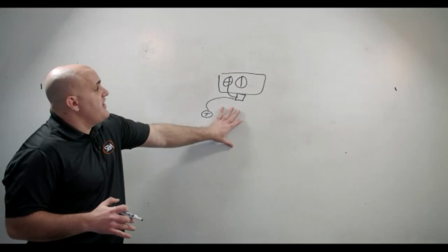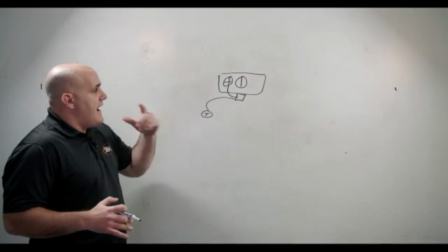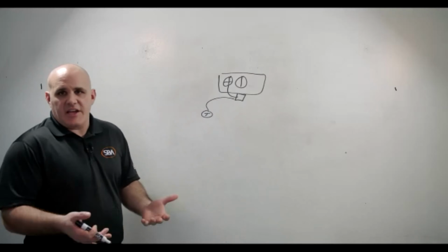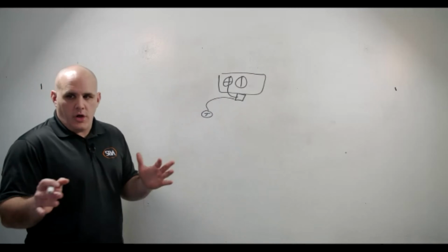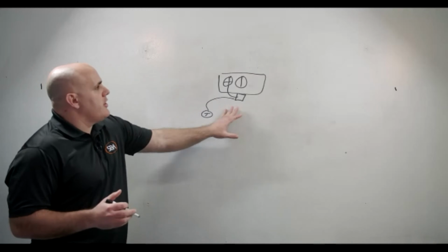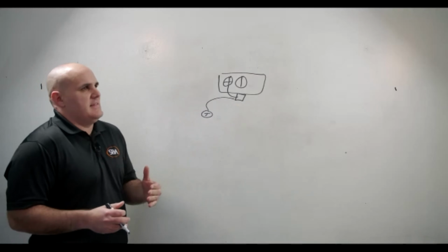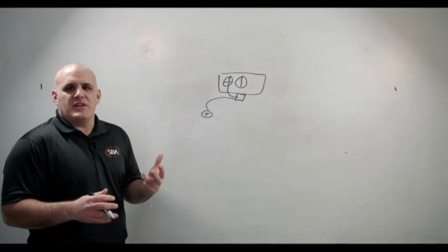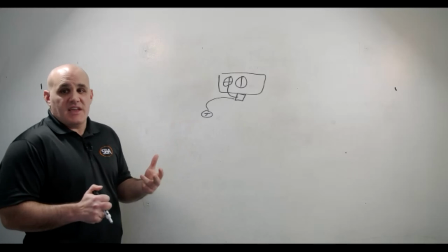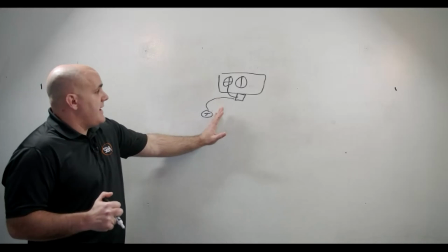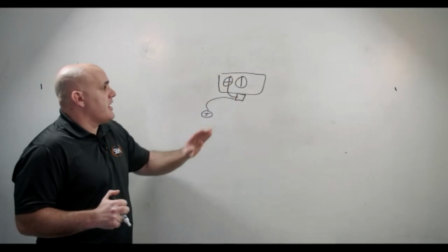All right, so with this VAV box, right, first off, VMA is an application-specific controller, right? It's got the actuator built into the controller. We're all aware of that, right? Okay, awesome. So we've got this controller, and it really has, if we're honest, two points, I would say, that we can go and really change things up, okay? So the first thing is our temp sensor, and then the second thing is going to be our airflow sensor.